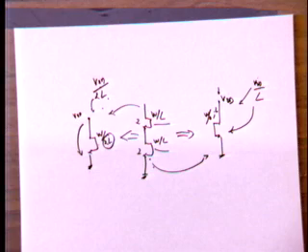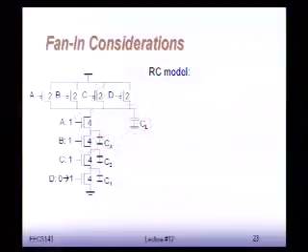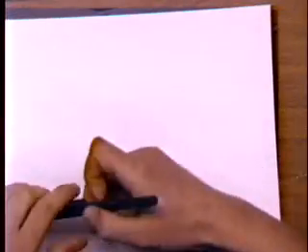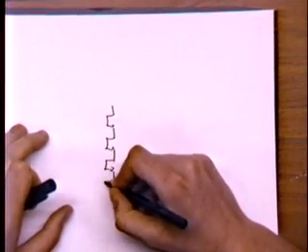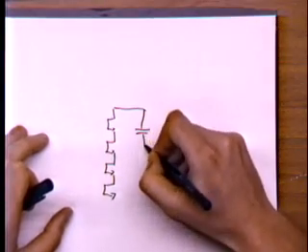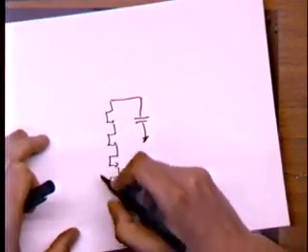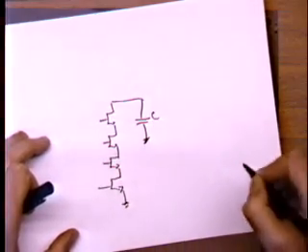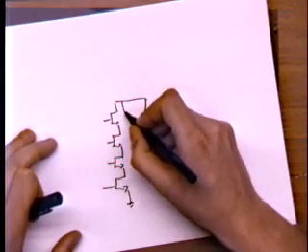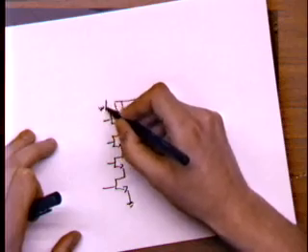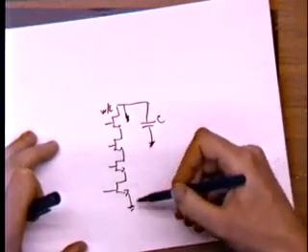So another interesting question is, how do we model, again, the delay of a complex gate? So far, let's stay with overhead, what we said is that the delay is still going to be given by the equivalent series resistance, let's say, of the pull down times the load capacitance, right? So let's do this thought exercise where we take devices of a fixed size, W over L, and we start making a more and more complex gate, right?